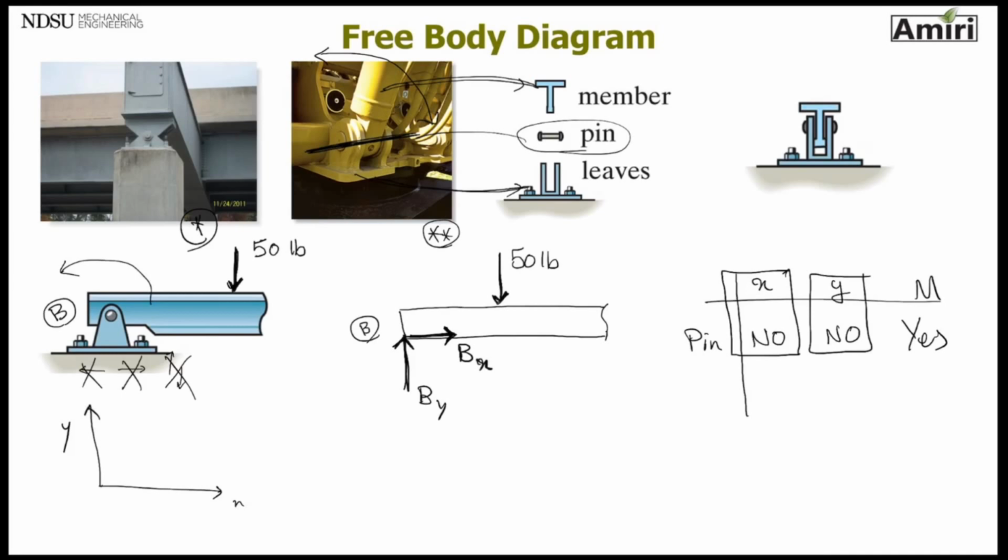Some of you might be wondering which way I put it, or how did I know it's pointing up, pointing to the right. At this point, it does not matter. At this point, I just like to put them in my positive axis. But when we get to the examples, I'm going to explain it does not matter which way you put the unknown reaction forces if you cannot figure out which way they're pointing. So we're going to talk about that. So don't worry about the direction yet.